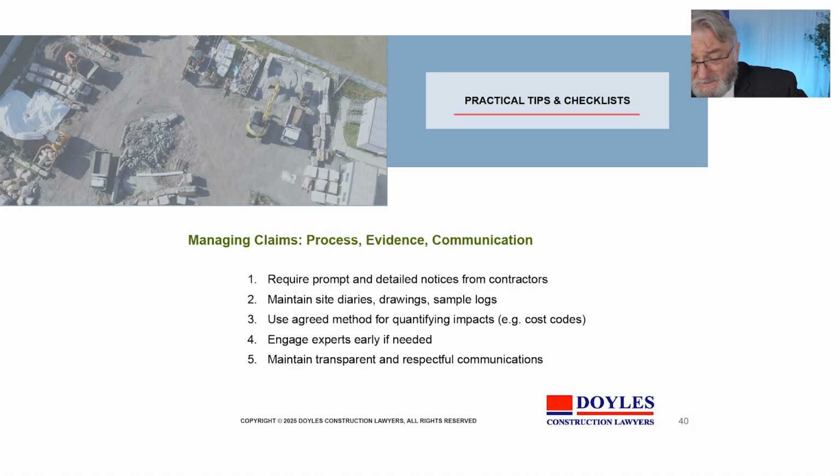Managing claims, you'll need to do the usual things to manage claims and make sure that you're in a state to have prompt notices from contractors, maintain your site diaries, drawings, photographs, have an agreed method for quantifying the impacts. At least have a record of the amount of material that's being carted, either off-site or otherwise. Engage experts, perhaps neutral experts early, in order to understand the matter and maintain transparent and respectful communications.